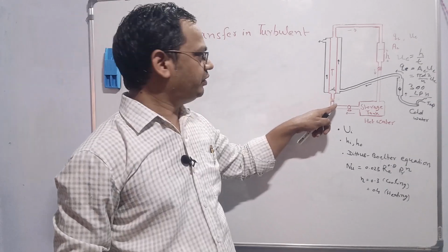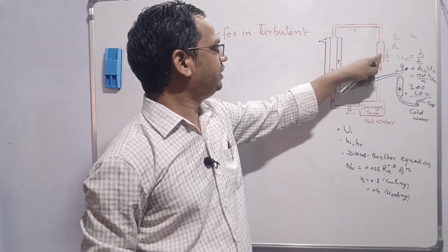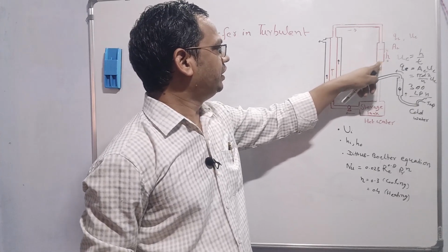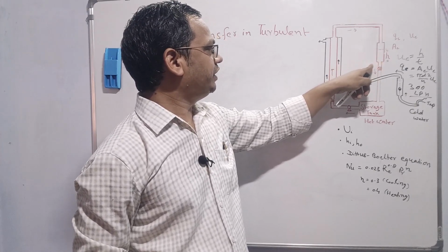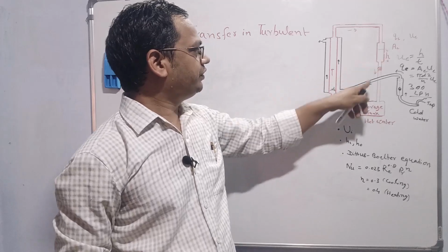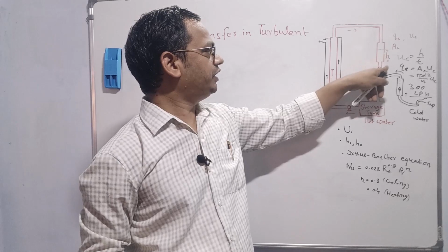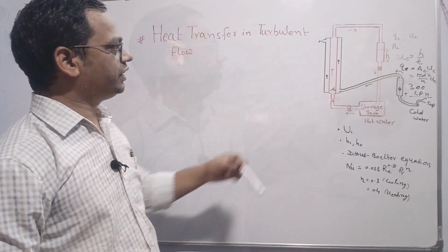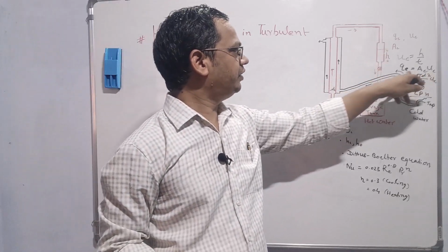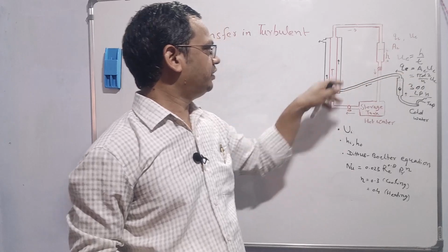Using this control valve, we can adjust the filling rate so that time should not be more than 3 seconds, or whatever in your case after calculation. Similarly, you can do the calculation for the minimum volumetric flow rate if you have a rotameter. In that case, in place of velocity, you can put volumetric flow rate by area.